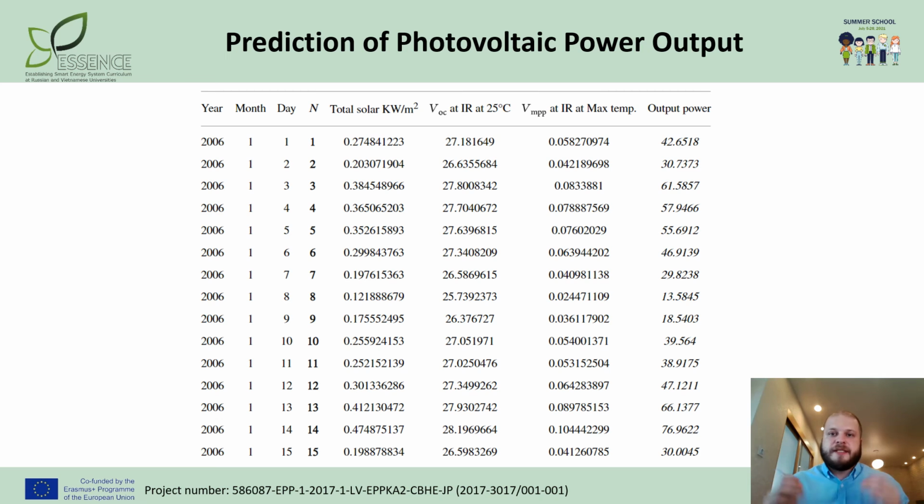So just think about it and exclude those features which will not be helpful for you in creating the neural network model, because some of the features will never be available for you if you provide the forecast of the photovoltaic power plant for day-ahead perspective.